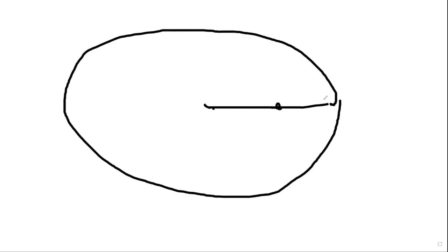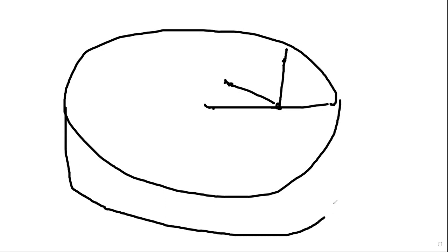Anything inside this circle will be reachable, because you can bend your arm to a certain location, and that one can go down, say, as far as 1 meter. So it's a cylinder. That's the whole workspace you can work on. In terms of workspace, you can describe something like that, and then you model this guy.